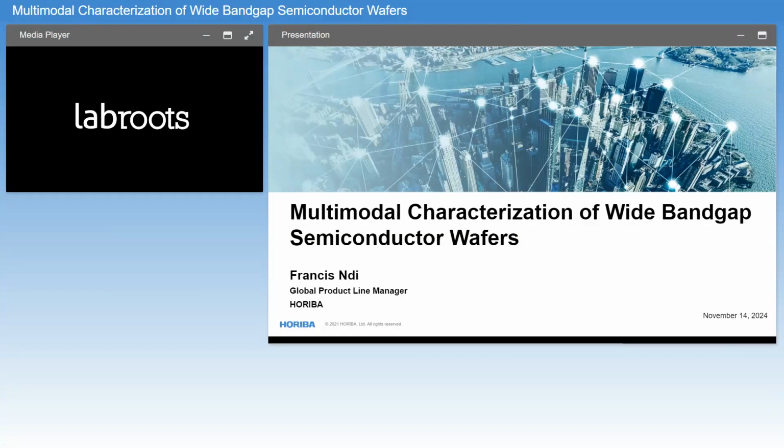And then we will move on to focus on the yield challenges that are common in the fabrication process. For each of these challenges, we will consider example cases of the optical spectroscopies and other modalities that are used to both characterize the materials as well as help address fabrication deficiencies. The techniques that we'll consider today include Raman spectroscopy, photoluminescence, time-resolved photoluminescence, cathodoluminescence, and laser scattering, among others.